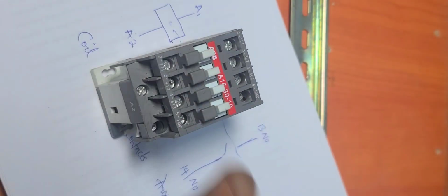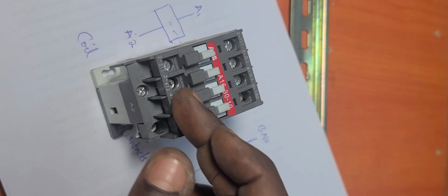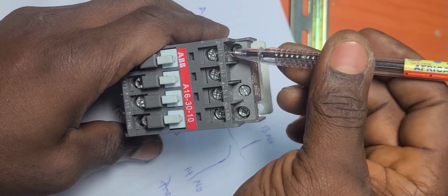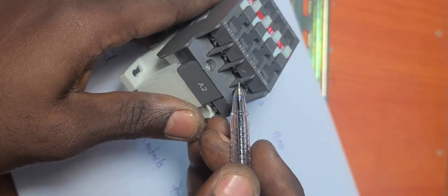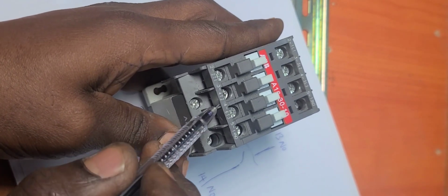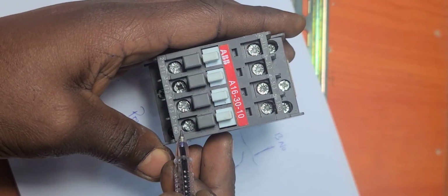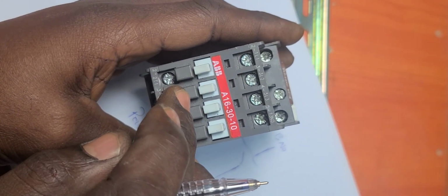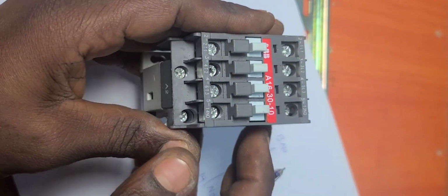So now, someone was asking, how do you connect a three-phase load to a contactor? It is very simple. Your three-phase power line is going to come inside L1, L2, and L3, while the three-phase power line of your load is going to come in here, which is actually T1 here, T2, and T3. This is exactly how you connect it. Then what you do with your auxiliary contact is now your choice. If you want to use it to control the operation or the behavior of the next contactor that is working together with this one, it is up to you what you do with it.